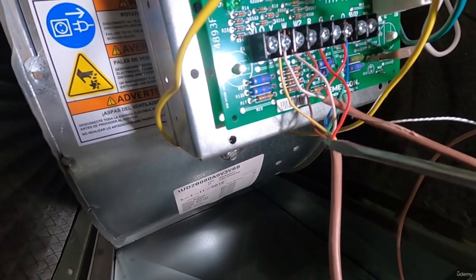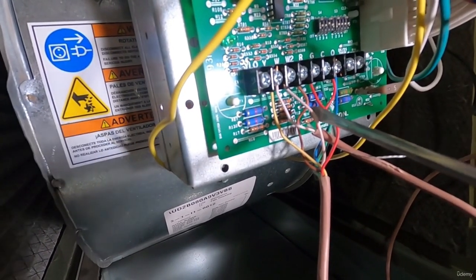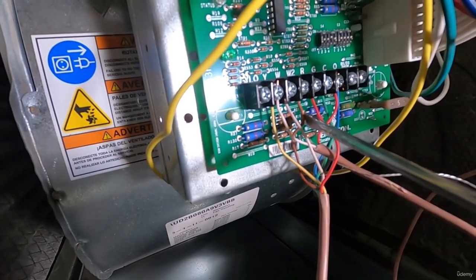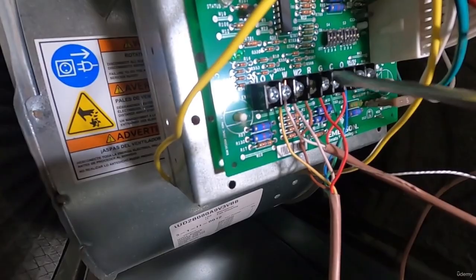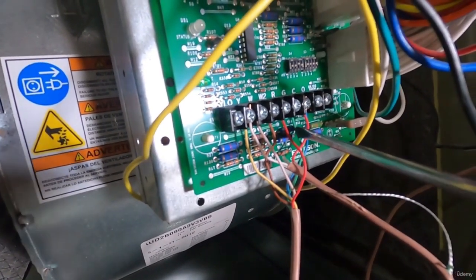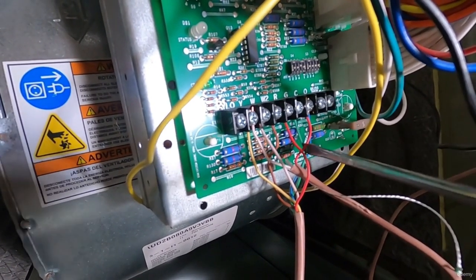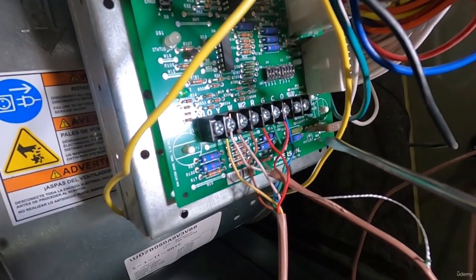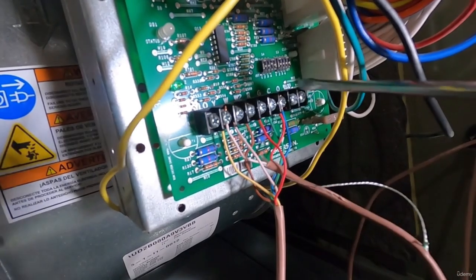But the other wire is coming down. Here is the W for the white heating circuit. This one is a brown for W2. This furnace happens to be a 2-stage furnace. You've got your red, the R, that's the 24 volt power going up. And then you've got your green, which is your fan circuit. And then here is your common. And again, you got the blue common wire going up to the thermostat. And again, the other red from the condenser going to the common.